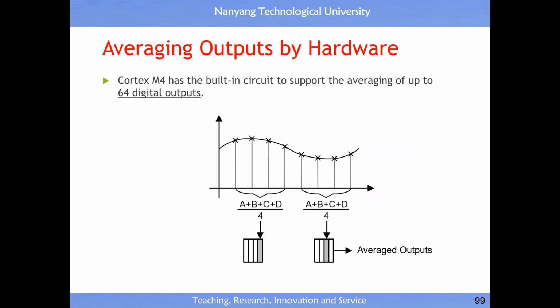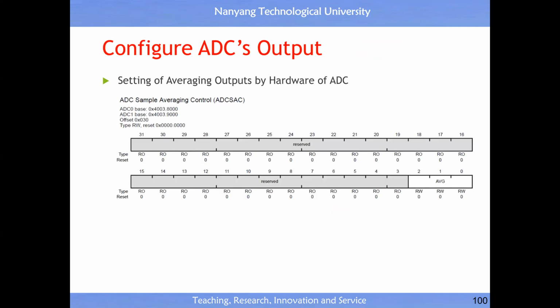They allow you to average out the output and produce a single output, and this does filtering in a noisy environment. Do the average, then actually you can remove the noise. So you can average up to 64 values, compute an average, then produce a single output. So this is really like a sports car when you just want to use a bicycle.